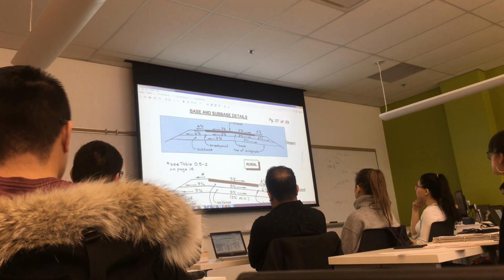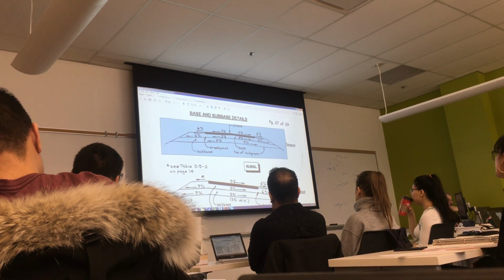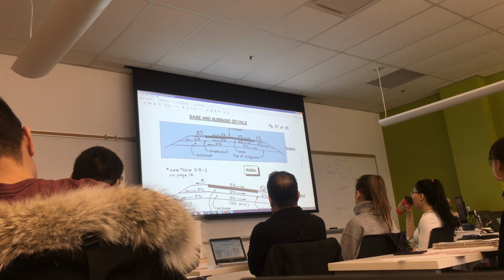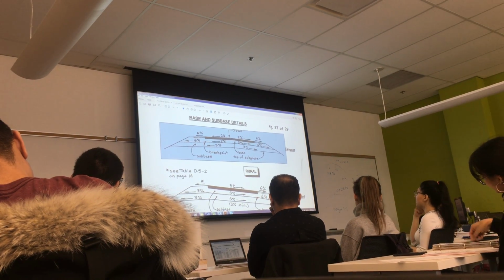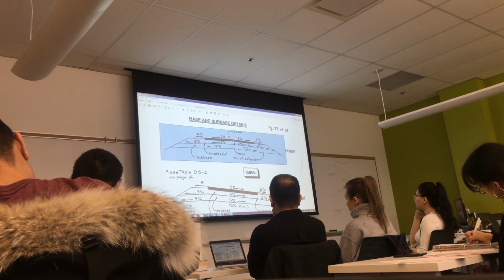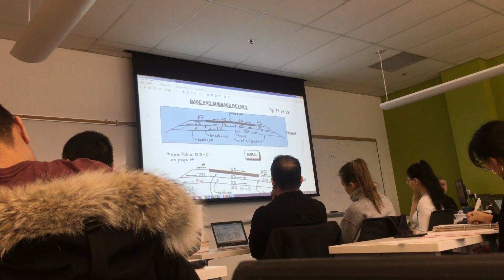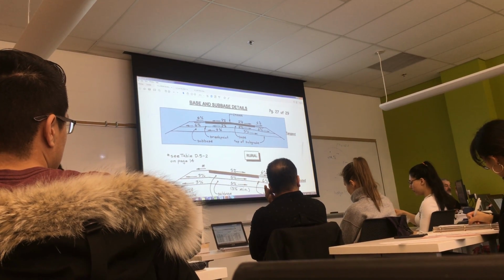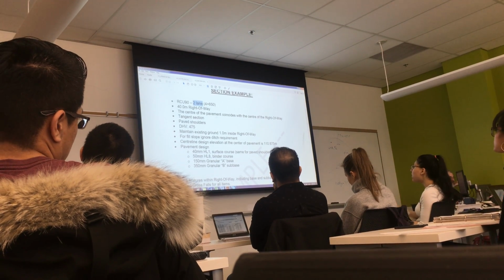It tells me the crossfall of the asphalt pavement, it tells me the shoulder crossfall, it tells me the subsurface layer crossfall, it tells me the subgrade crossfall. Okay? So I'm going to use this information. This is the generic piece of information you need for slopes, and together with the pavement structure that's required, you're going to use both of those pieces of information in combination.